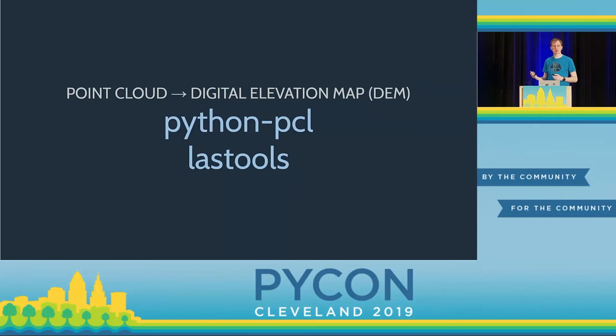In particular, there is a thing called the Point Cloud Library, which is a very good way of handling point clouds, not only in terms of reducing them down and making them easy to work with, but also extracting height maps or 3D surfaces. There's also a standalone program called LAStools. It's not free, but it's free for small amounts of data. That's much more of a plug and play. Give it a point cloud, it will dump you out a height map. No real sort of extra Python work required.